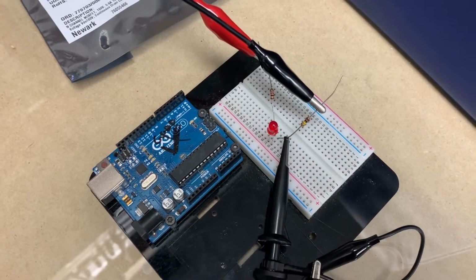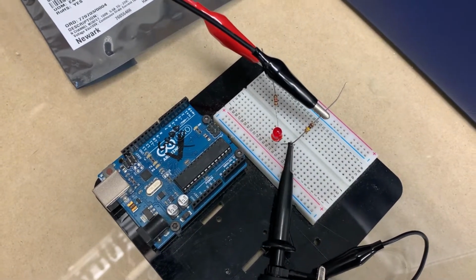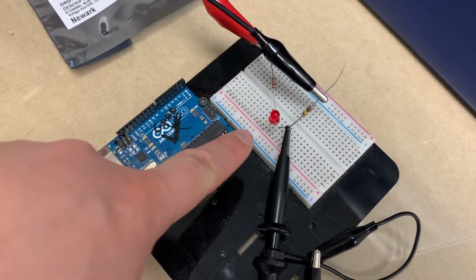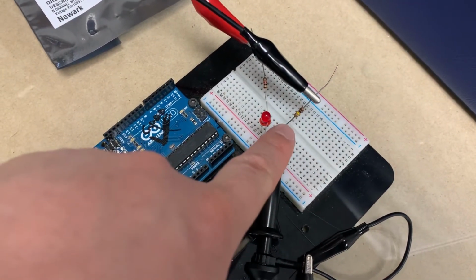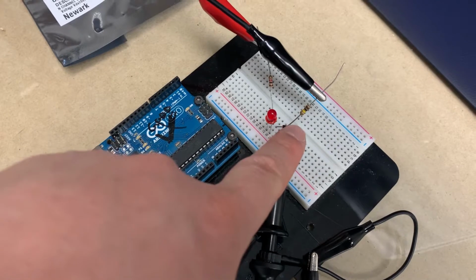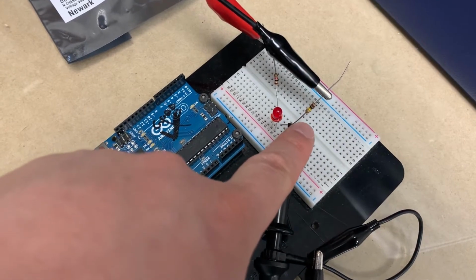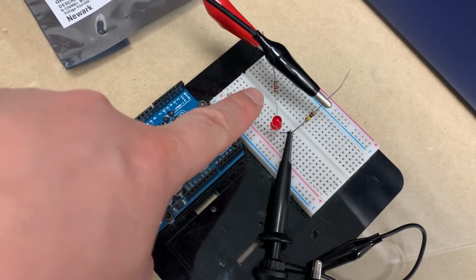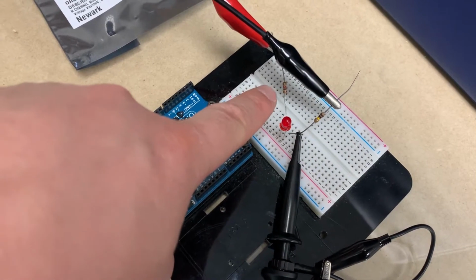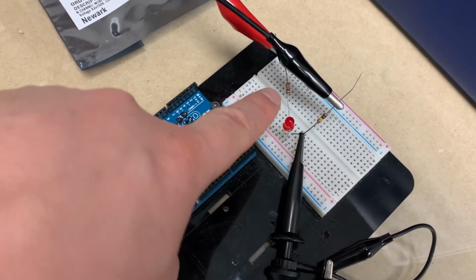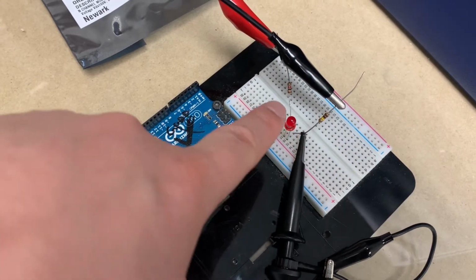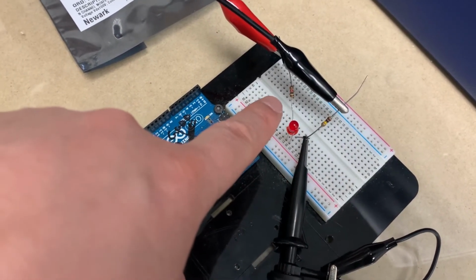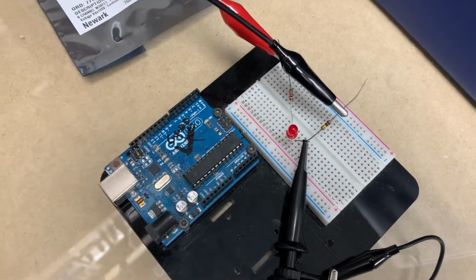What I have here now is a very simple circuit setup. I have the LED acting as a SPAD and also two resistors. On this side, we have a load resistor that I put a 100K resistor in there, and also a bias resistor, which is a 1K resistor. Now, I could play around with the resistor value to get a different reading, but let's see if we can actually get some reading first before we play around with the value.